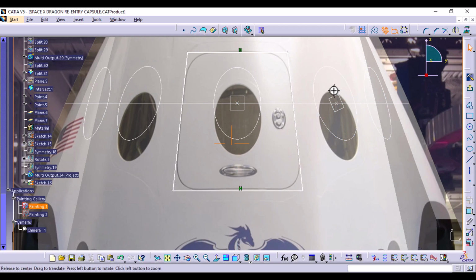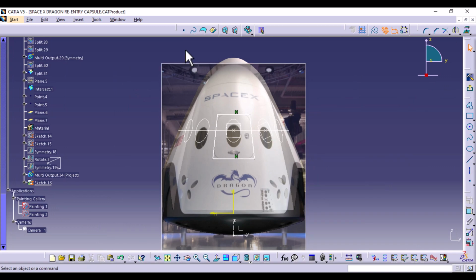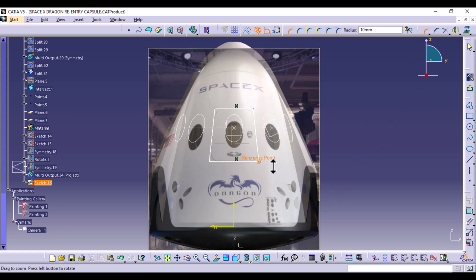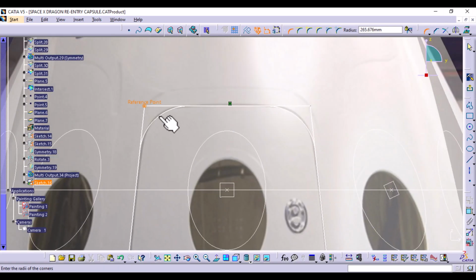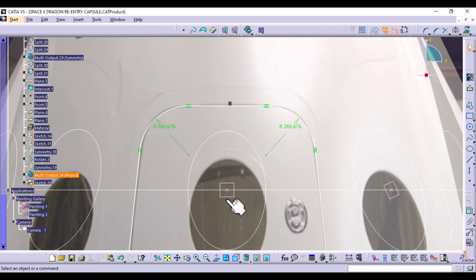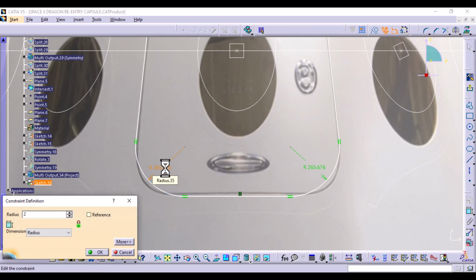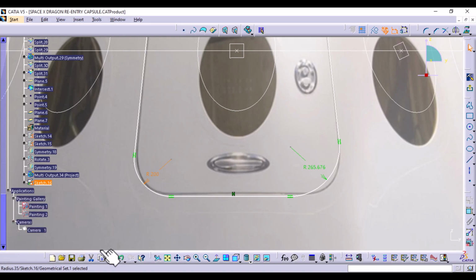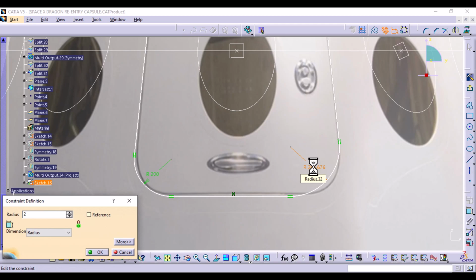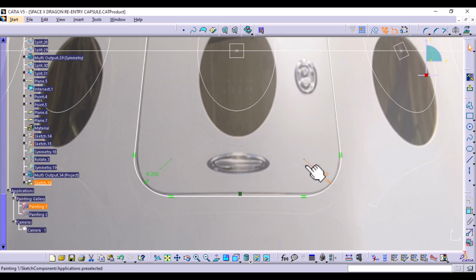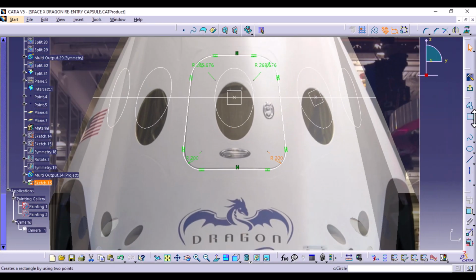All right. Then we can select everything and insert corners. So the corners like that, but the ones down below, we're going to have to reduce the radius. We're going to go with 200. Same thing applies on the other side, 200. That's a nice shape, okay.